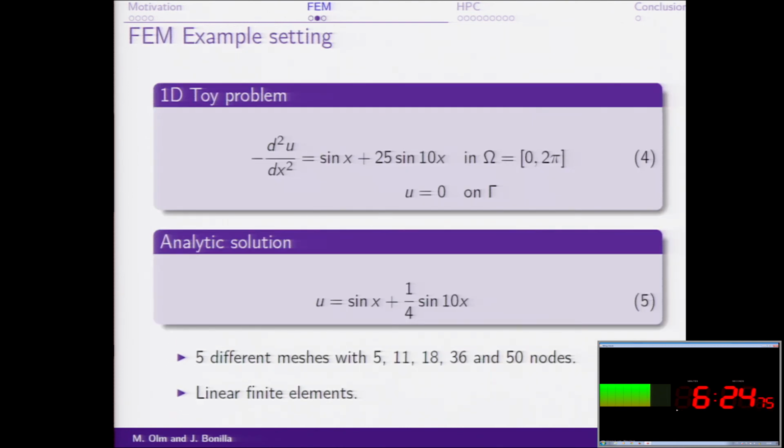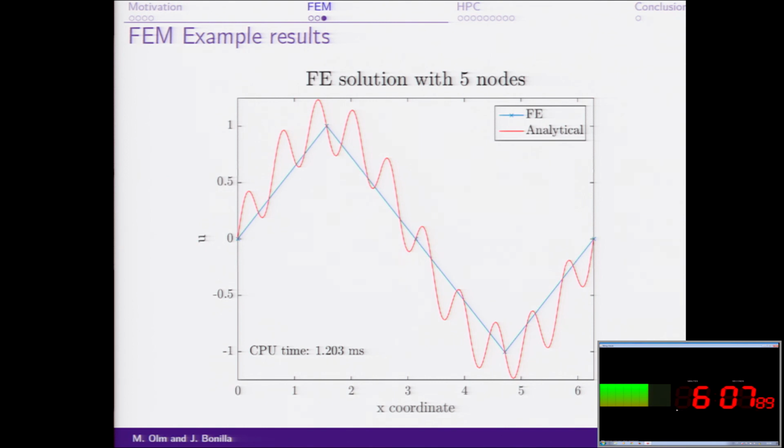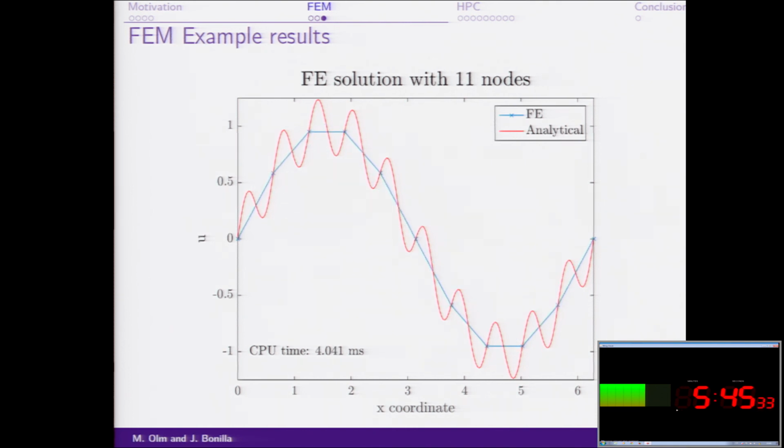And for example, to show a toy problem, a small example, imagine the same equation, the heat flow in a rod, that is so simple that we can do it by hand, and this is the analytical solution. And we have performed several tests, including more nodes. It means making smaller and smaller parts. So this is the first approach in blue, the numerical solution. It's just a crude approximation. It just captures the general behavior. But if we add more elements, the solution improves.